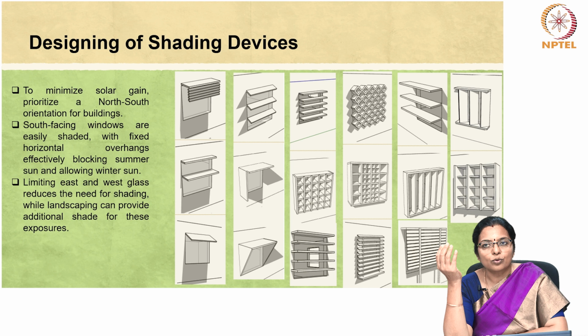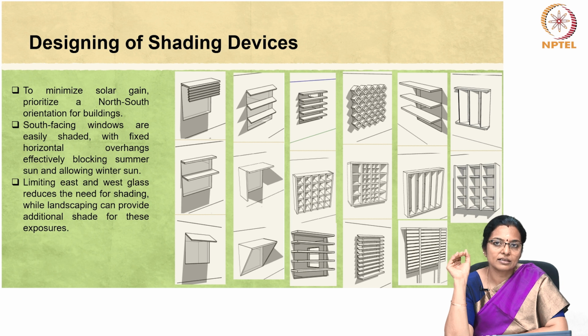An extended roof can provide shade to the entire north and south wall from the noon sun. Shading generally is not required on the north side as much as it is required on the other sides. Only cutting the low evening summer sun can be achieved by vertical shades or internal blinds.